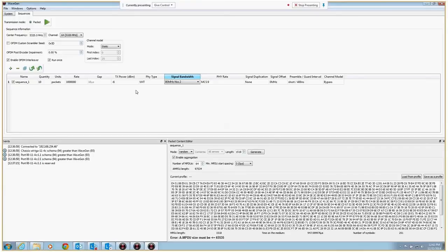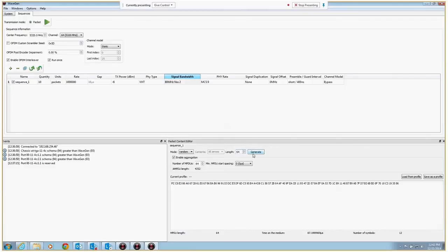So my point here is that as you are diagnosing and troubleshooting, one of the problems with vector signal generators is how long it takes for you to do the next experiment that occurs to you. And here it's very simple. You just point and click. So you can do all the sleuthing that you need to. If you wanted to change the length of your frame, maybe it's a long frame issue, maybe it's a short frame issue. Now you can go and take a look at that. Now that's your ability to adjust and troubleshoot one given situation.